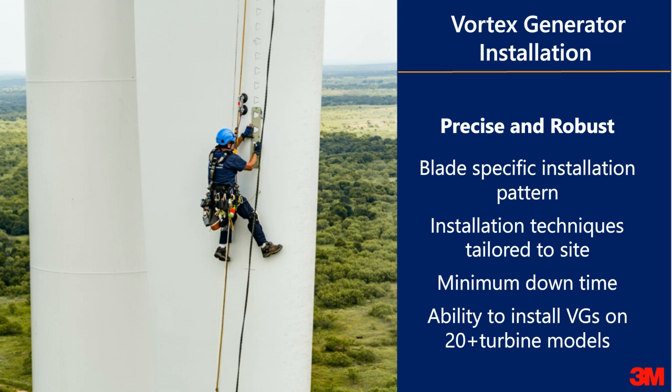If you look at this picture, you see the template. That's how we ensure that we have a precise installation. For every different turbine model, we have a different template that our teams use. And when we're doing rope access installation, we actually have two rope access technicians working on the blade. One starts at the root, and one starts down by the tip, and they meet in the middle, and they work in conjunction to install the VGs to ensure that we're following that specific installation pattern.